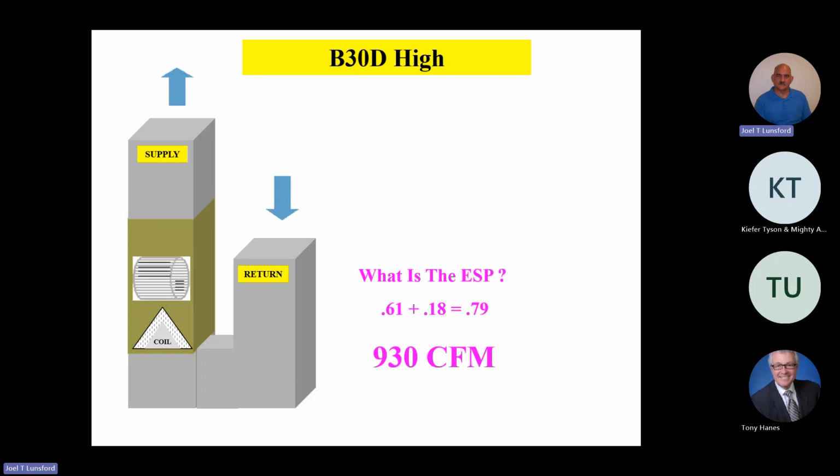That way you can start utilizing your magnehelic gauge and your static pressure as a troubleshooting tool as well. And in this example here, we are light on airflow. There's something going on the supply side. So that's where I'd start looking. Any questions or comments on utilizing static pressure and the factory airflow charts to find airflow? Any questions or comments? Yes, one second.